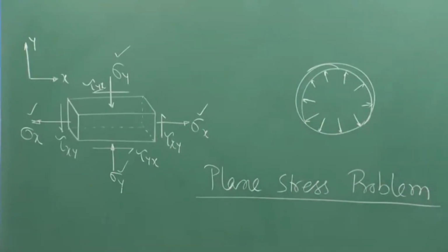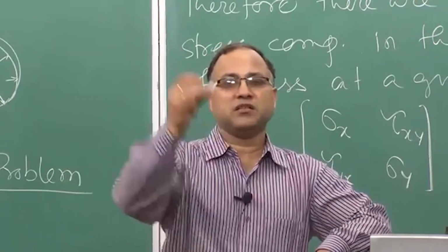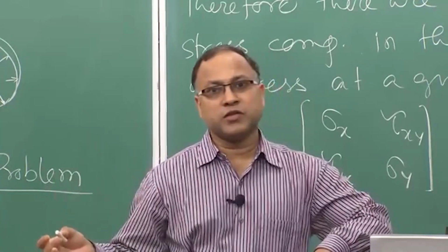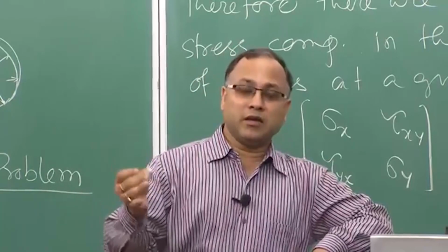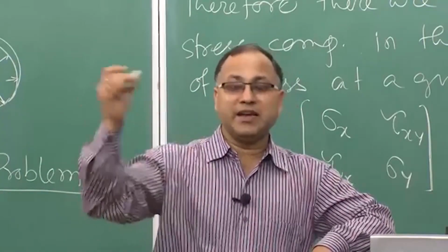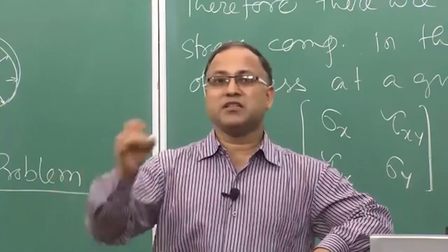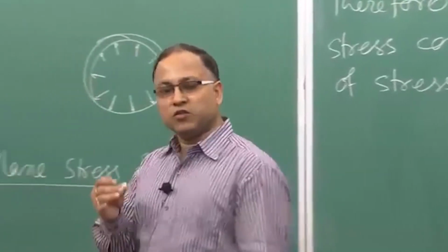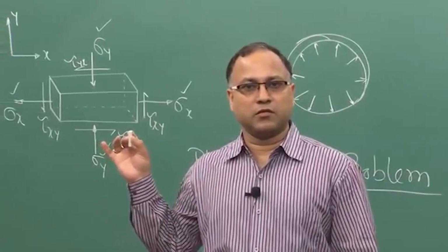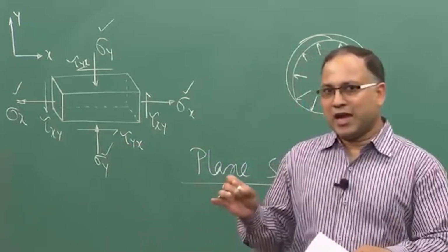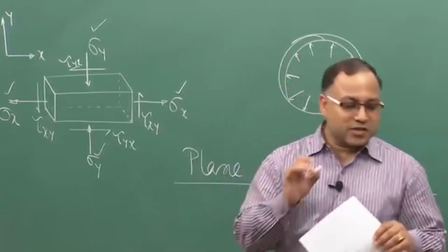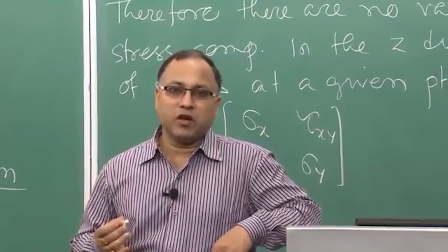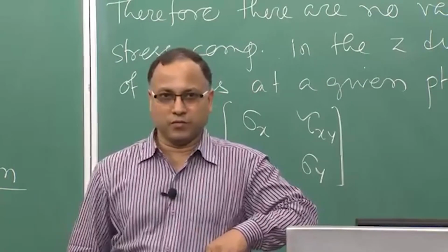Okay? Fine. Similarly, the shear stresses will be defined like that. If it is acting on a positive plane in the positive direction, or a negative plane in the negative direction, then that will always be positive. But if they are acting on a positive plane in the negative direction or a negative plane in the positive direction, then they are negative. So, this is the sign convention you will be following throughout the course. Okay, I hope you have understood. I have spent enough time on the sign convention, because people generally make mistakes with it. So, I do not expect this kind of mistake from you.